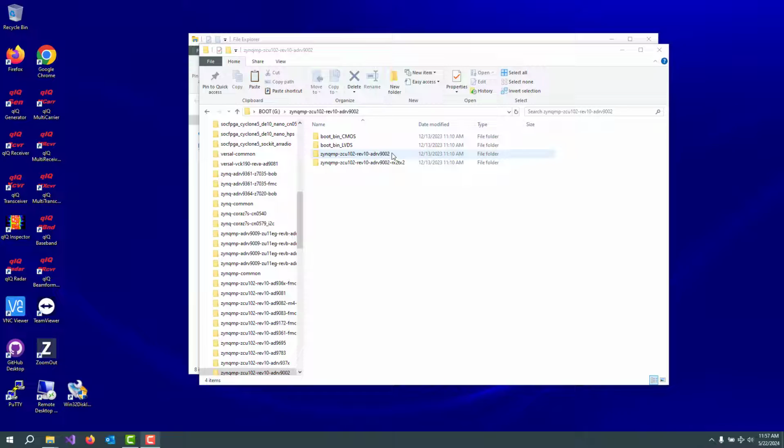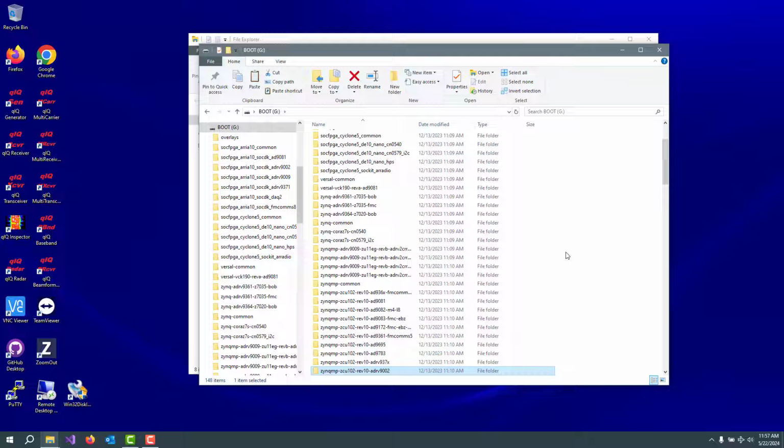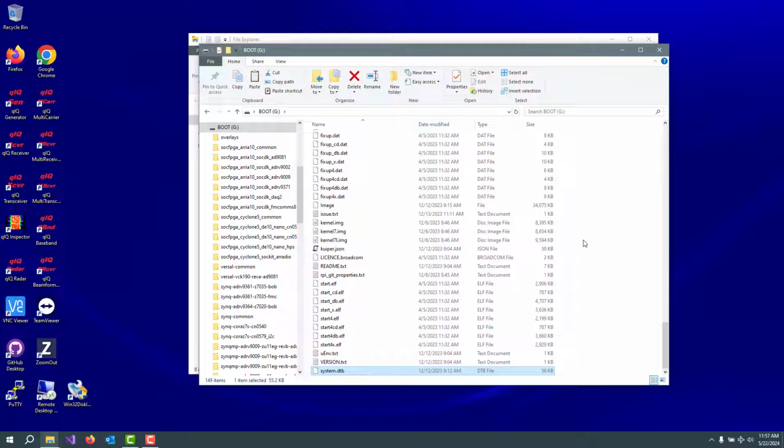This is known as the independent mode, and this is known as the MIMO mode. Why they're not marked independent and MIMO, I have no idea. But we want to go into this one and take our system device tree and copy that and put that into our root directory. Alright, so we have now created the bootable SD card image for the ZCU102 board.